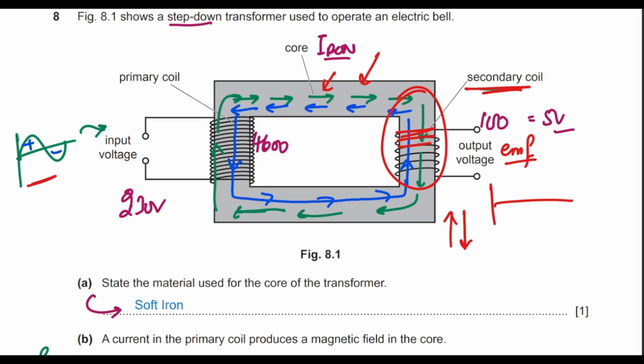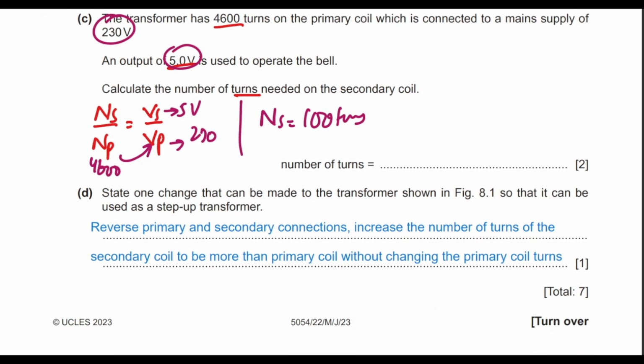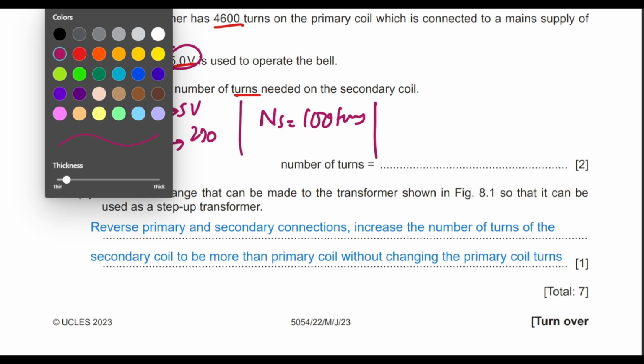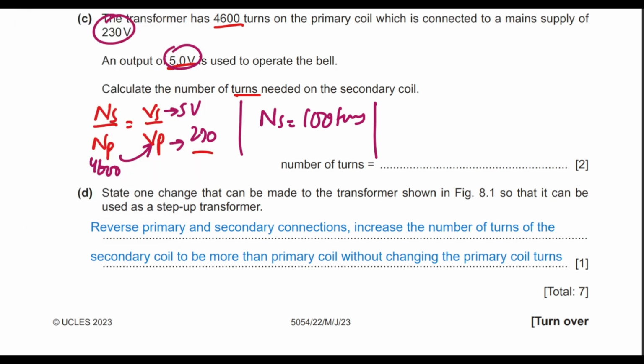So basically you can say that this question is for mobile phone chargers. That is one transformer that they have inside them that takes 230 volts from the source, from your electric supply company, and brings it down to 5 volts, which is safe for the mobile phone battery charging. So the number of turns that is going to achieve this is 100 on the secondary side.